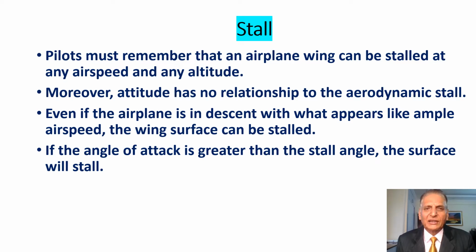Pilots must remember that an airplane wing can be stalled at any airspeed and any altitude. Moreover, attitude has no relationship to the aerodynamic stall. Even if the airplane is in descent with what appears like ample airspeed, the wing surface can be stalled. If the angle of attack is greater than the stall angle, the surface will stall.